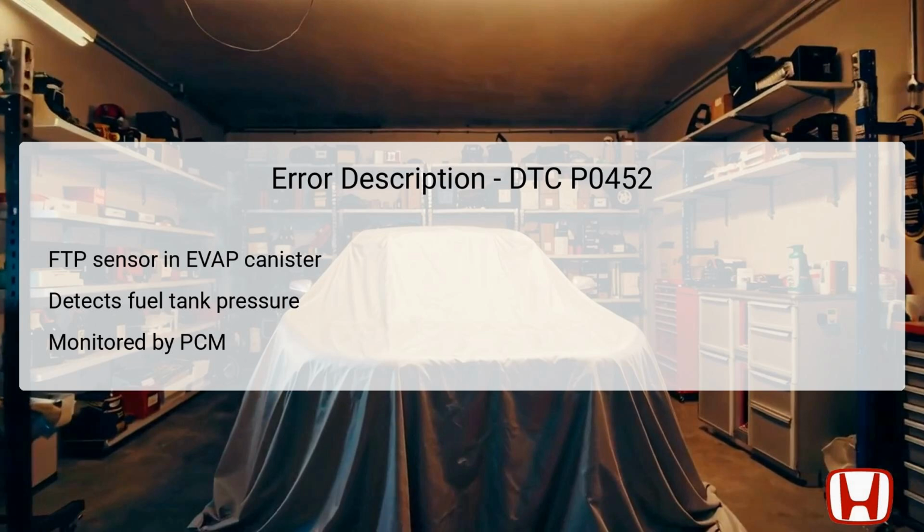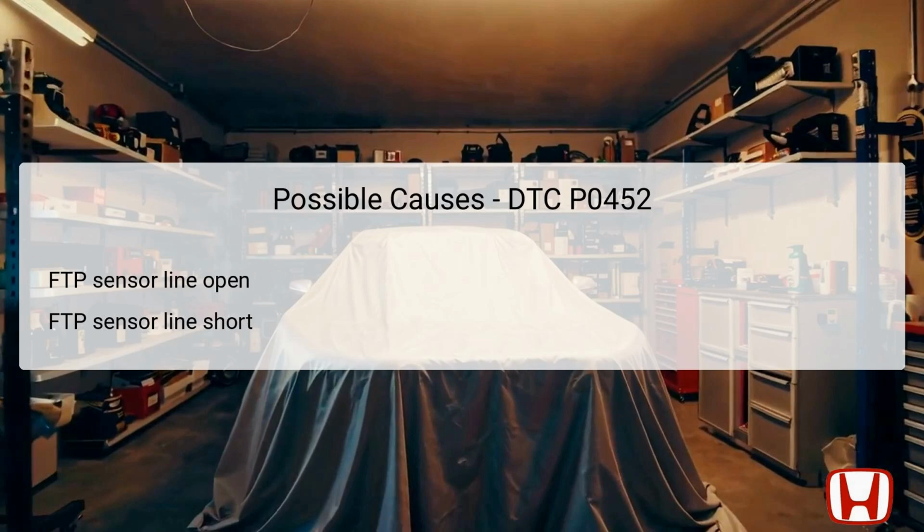The information from the FTP sensor is sent to the Powertrain Control Module (PCM), which utilizes this data to monitor the integrity of the fuel system. Specifically, the PCM will measure the sensor's voltage output. This voltage should rise and fall according to the fuel tank pressure. If the sensor's output voltage does not reach the expected levels, the PCM concludes that there's a malfunction, triggering the DTC P0452.